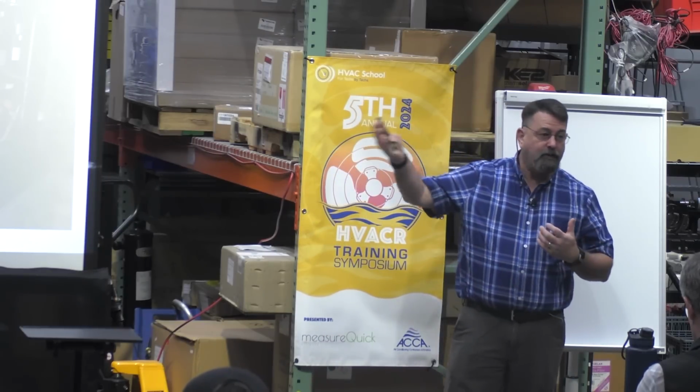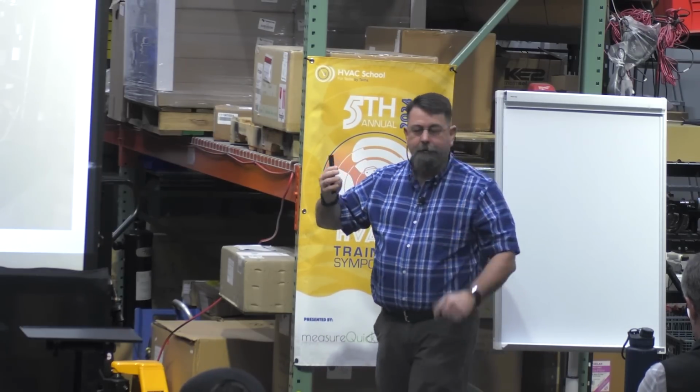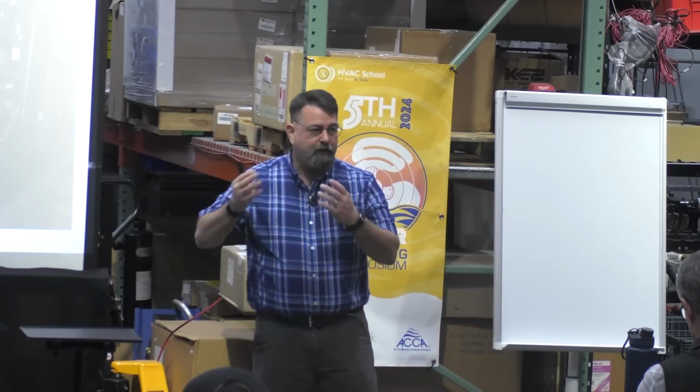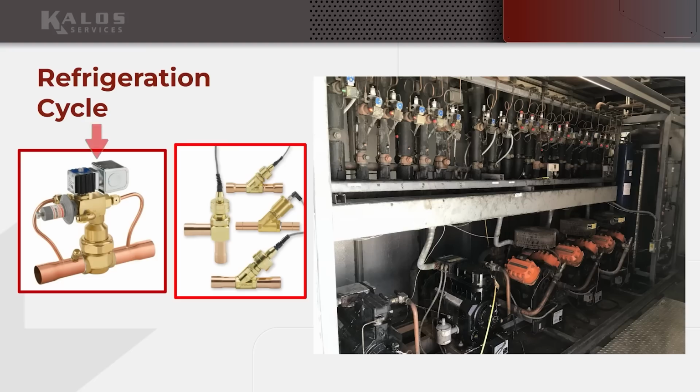That way I only need one set of controls to turn them on and off, right? I'm going to refrigerate them with the same liquid and suction line. That means I'm going to have one EPR controlling that suction pressure to all 6 cases, right? So it just makes it a little simpler. Makes it a little cleaner, right? So that's my EPR. I've got a modern version.